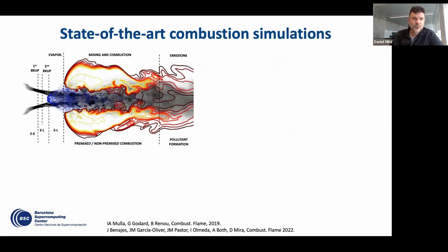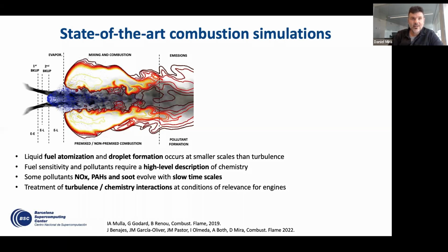So as a start, let me give you a brief overview of the combustion physics that we are trying to target in combustion systems. In general, the fuel that is used for aero engines is currently liquid kerosene for most applications. This fuel has to be injected into the combustion chamber, usually at high pressure. In this case, the fuel has to atomize from the liquid vein. It has to break into ligaments, filaments, and then eventually into droplets before the fuel can be evaporated and mixed with the air. So we have important challenges because this atomization process is quite complex, and it depends on scales and conditions that are quite challenging for numerical methods.